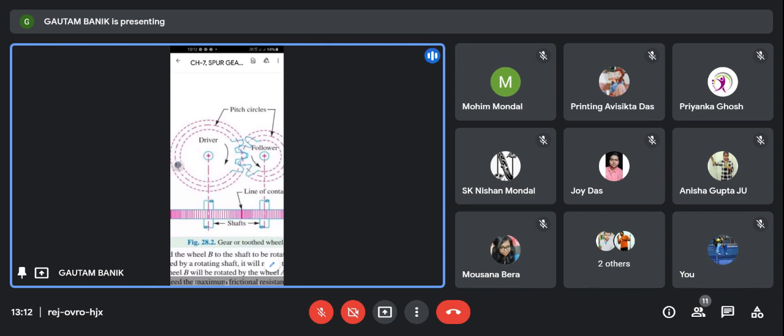Between two consecutive gear teeth there is a space, called the tooth space. When the two gears are meshed together, the teeth of the other gear will be introduced in this space, so their sizes will match together. Their dimensions we will calculate with the help of the module and the pitch circle diameter.